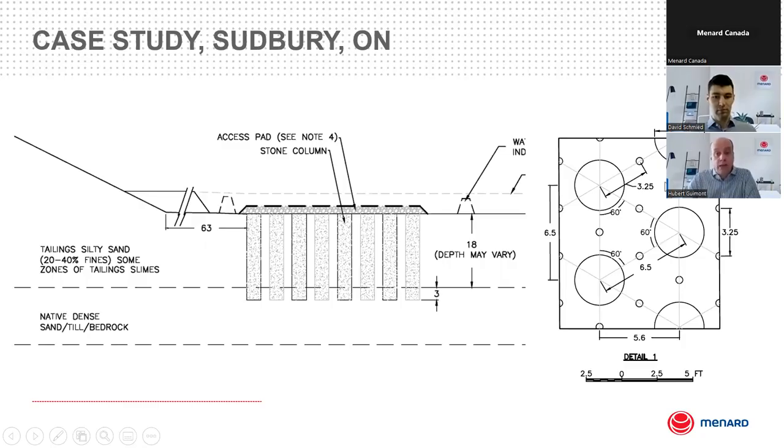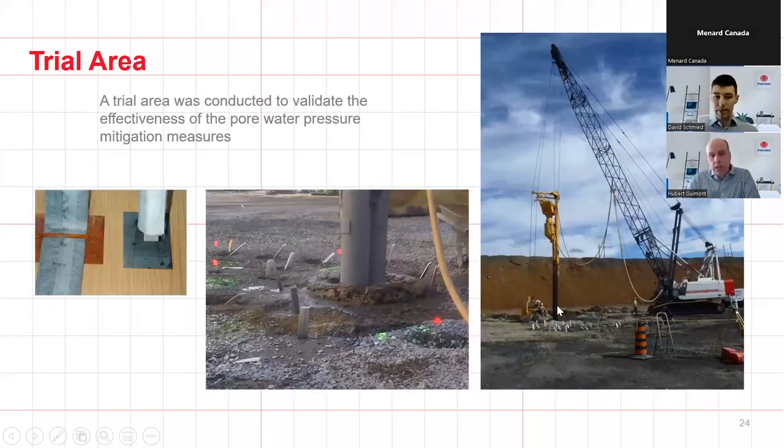The whole operation was really controlled and instrumented. We did real-time monitoring during the installation. We also did a trial test in order to make sure that the monitoring system and the pressure relief well were functioning well. That's always a concern when you're working with a sensitive installation and you want to treat for liquefaction at the base of the dam, right? So we started with a pilot test, a trial area right there, making sure that all the monitoring instruments were working fine and the procedure was performing the way we were expecting.